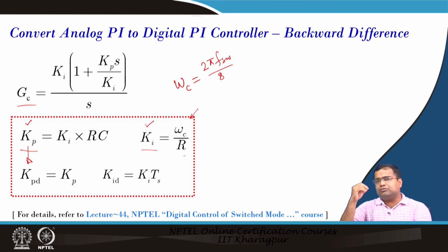Another way, they can use an analog comparator by means of a voltage hysteresis, so that if the voltage goes beyond this band, then they can either increase the sampling rate, or they can suddenly create a step reference to anticipate the load transient effect. There are many ways, and in the next lecture, we will be discussing how to go beyond this small signal design, so that you can get a really very fast transient.